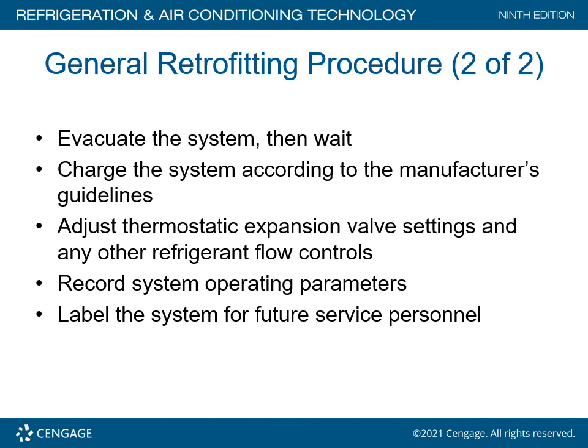Charge the system according to the manufacturer's guidelines. Adjust the thermostatic expansion valve setting and other refrigerant flow controls. Record the system operating parameters. Label the system for future service personnel. Now this last one, I have a real beef with a lot of service techs out there today because they use R22 alternative refrigerants and they do not bother to label the equipment that an R22 unit has been retrofitted with this chemical. This is something that must be done because here's the deal.